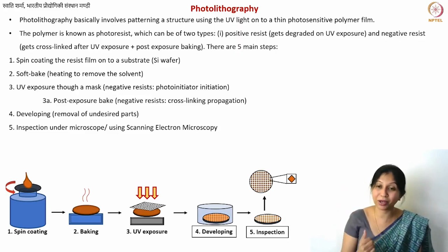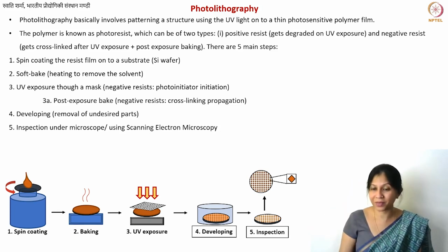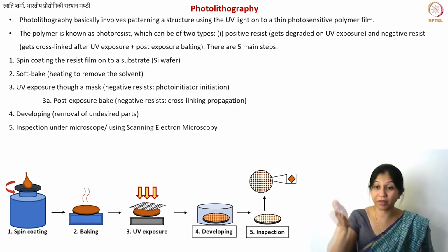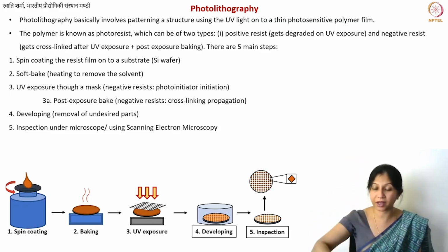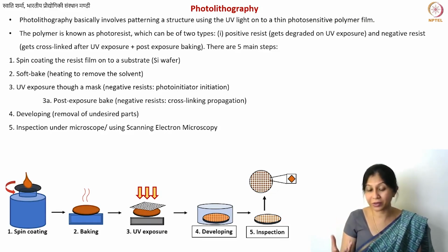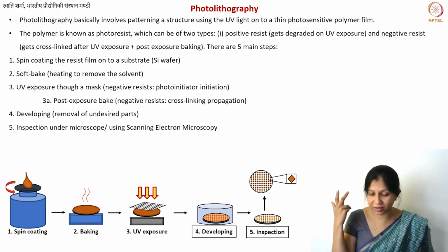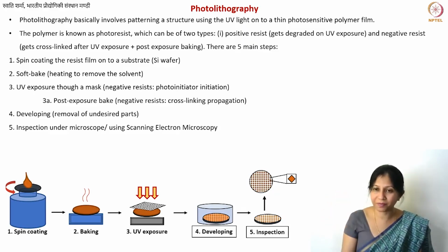But at the same time, it might be going through so much coking that you are losing the shape. So you can do multiple experiments. You can take the tip and keep it upside down also, and see if it elongates. The best case scenario is that your material goes through a semi-solid phase, but not so liquid-like a phase that it loses its shape. And phenol formaldehyde resins are traditionally used for this purpose. Traditional glassy carbon precursors, for a very long time.